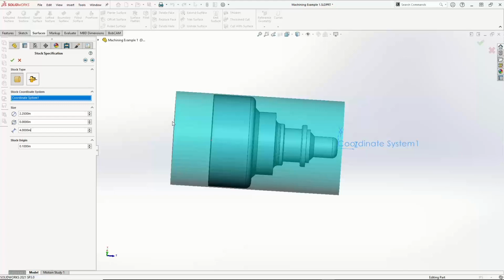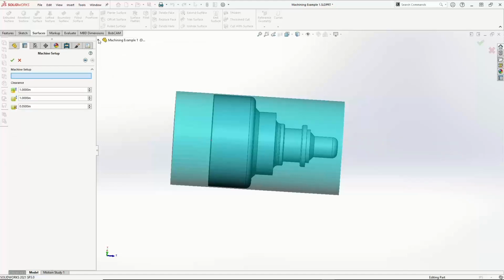All right, and it works just like the facing does in the milling setup, where you can essentially not pick any geometry. It's recognizing this material in front of the part as face material. It's material that has to come off, so you've got to make sure you set it up properly. Finally, the last bit is setting up the machine setup right here, which is our coordinate system.